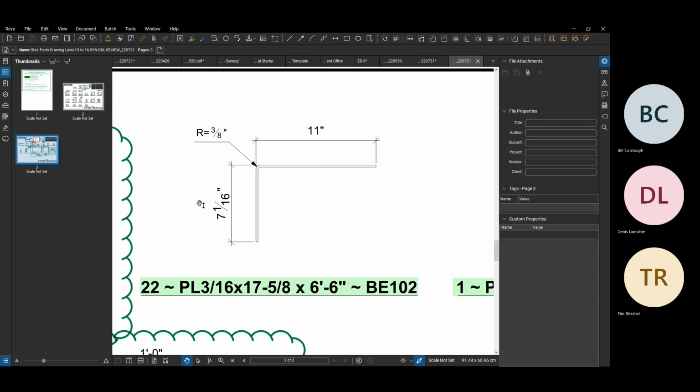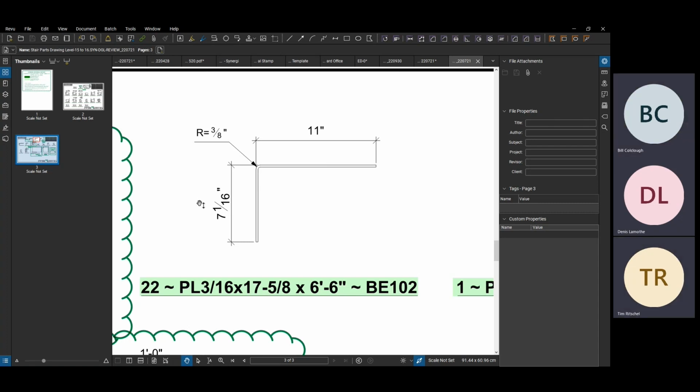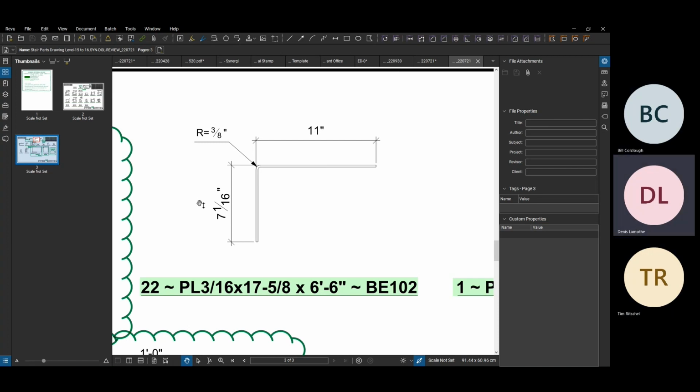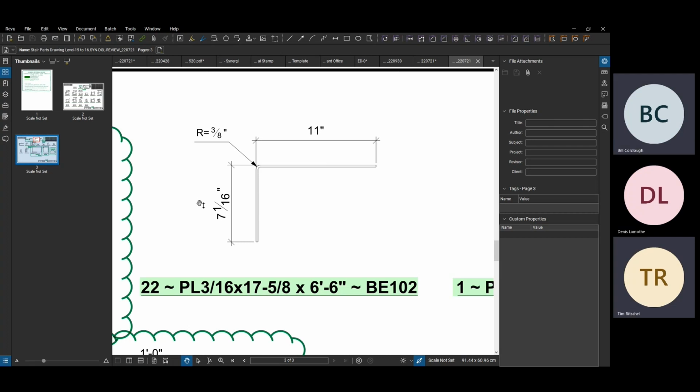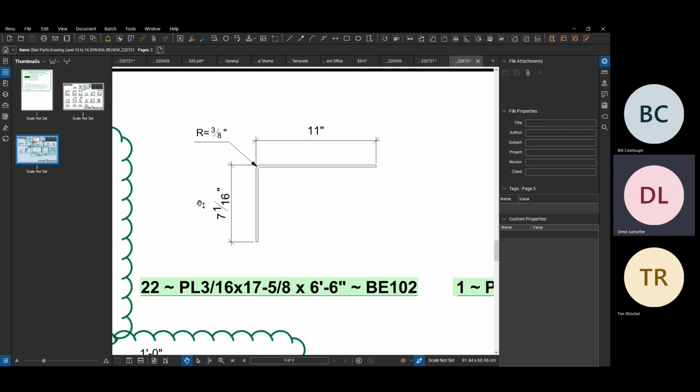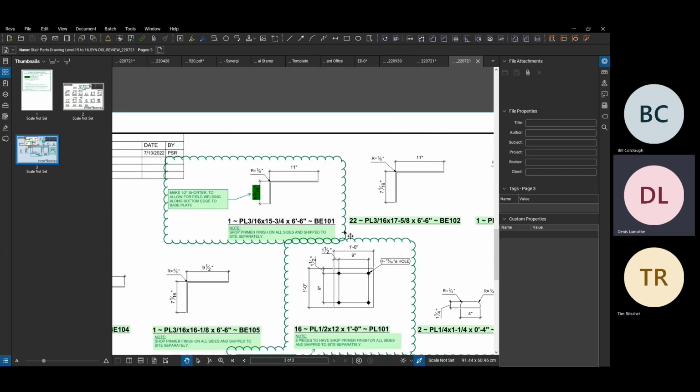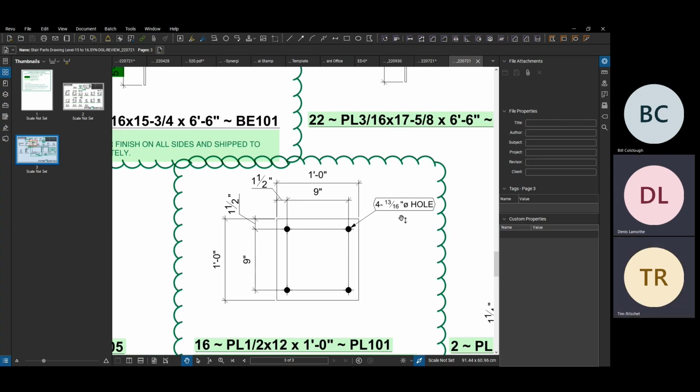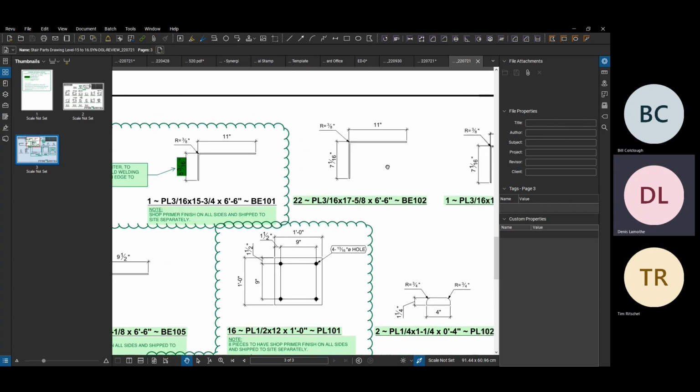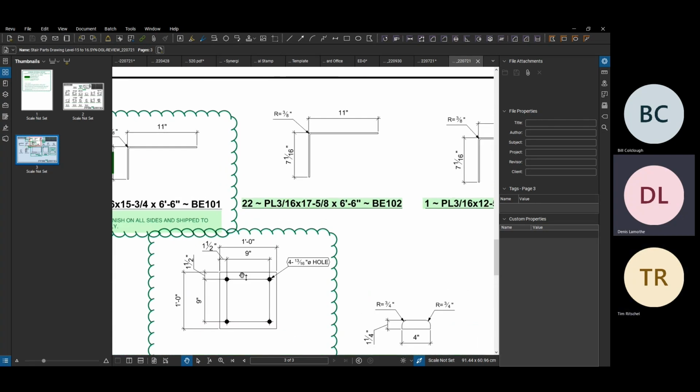So we are pretty comfortable with showing a 16th of an inch in terms of dimensioning. The only time I might, well, I'm trying to think if there's an exception to the rule. I may show a 32nd of an inch dimensionally if we're measuring a part that has 2 or 3 or more holes, and I'm dimensioning from center to center to center of the holes. I may want to round it to a 32nd of an inch just to show less of that dimensional creep if it's a rounding thing going on.